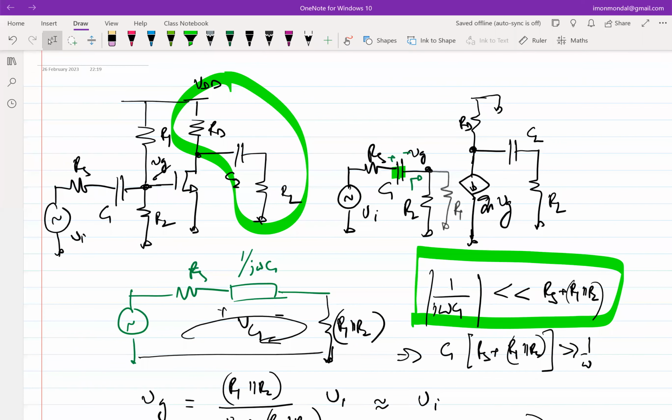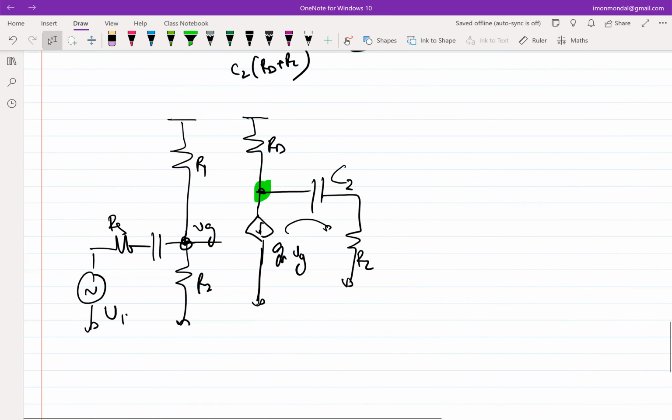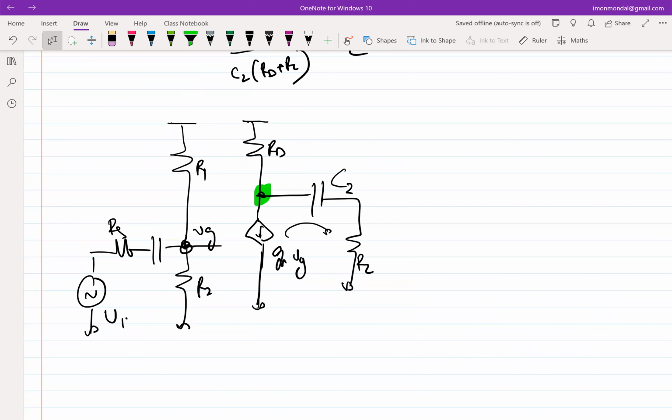If the transistor is in saturation, then the current drawn through RD will be constant, and if I keep on increasing RD, the drop across RD will keep on increasing, so the voltage across the transistor will decrease. Which means there is only a certain maximum value of RD that I can achieve under a given voltage VDD, assuming the transistor is in saturation. So I have run into a problem: this condition of RD being much greater than RL will only give me so much gain. Then I argued, wait, what if I could replace this RD with a current source?